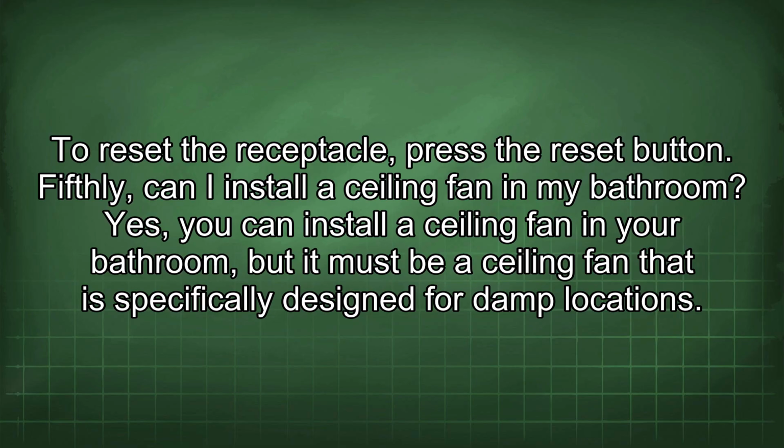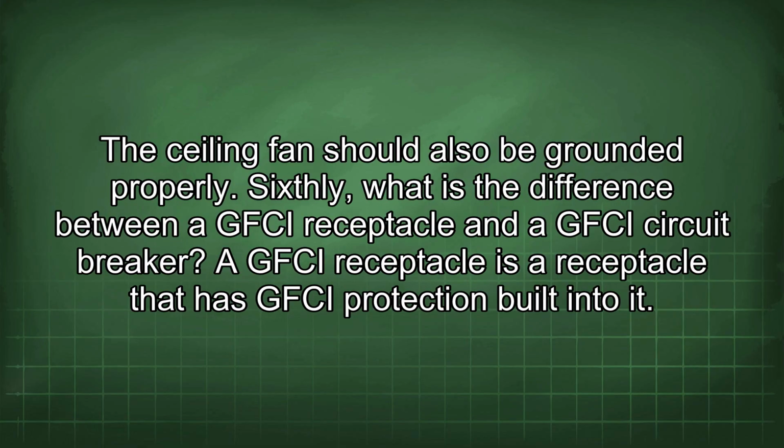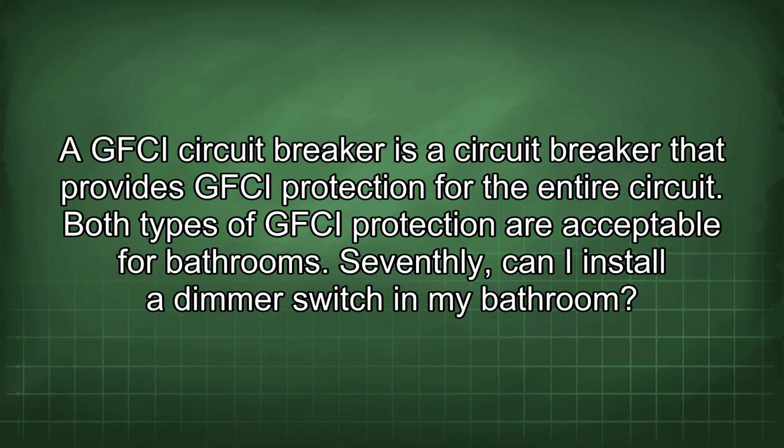Fifthly, can I install a ceiling fan in my bathroom? Yes, you can install a ceiling fan in your bathroom, but it must be a ceiling fan that is specifically designed for damp locations. The ceiling fan should also be grounded properly. Sixthly, what is the difference between a GFCI receptacle and a GFCI circuit breaker? A GFCI receptacle is a receptacle that has GFCI protection built into it. A GFCI circuit breaker is a circuit breaker that provides GFCI protection for the entire circuit. Both types of GFCI protection are acceptable for bathrooms.